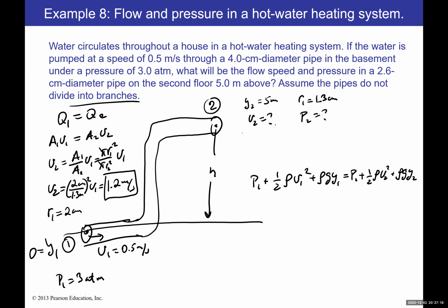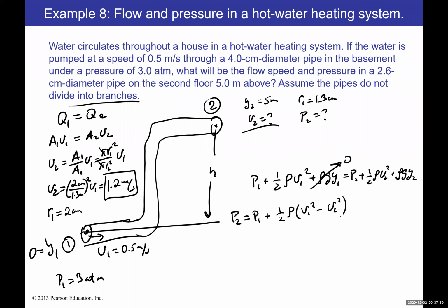So that means now I have one of the quantities. Then if I go back to this equation for the Bernoulli's equation, the only thing I don't have now is pressure 2. But I can simplify this a little bit by canceling this, because y1 is equal to 0. And unfortunately, that's the only thing I can cancel for now. But then everything else, I can just do the calculation. I can say then P2 is equal to, then move everything to the other side, right? Basically rearrange. So it's then P1 plus 1/2 rho times V1 squared minus V2 squared, then minus rho g y2.